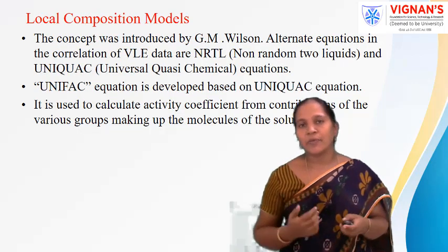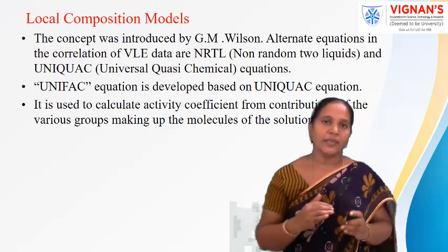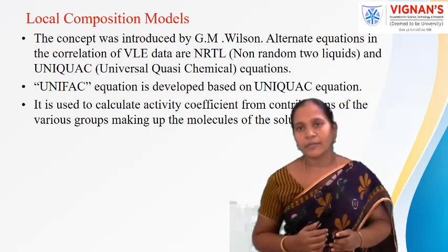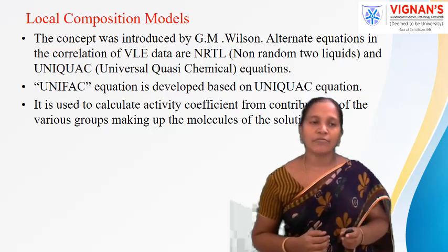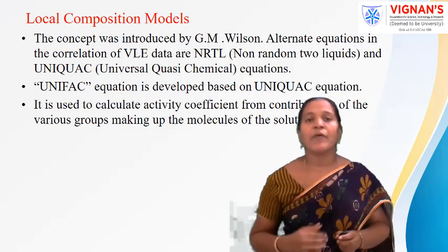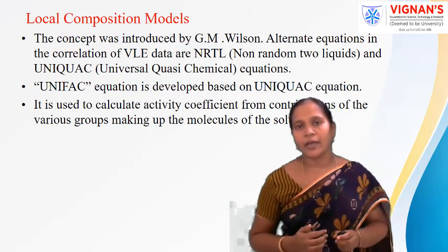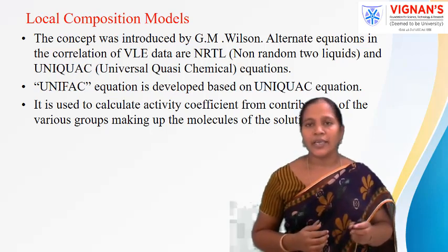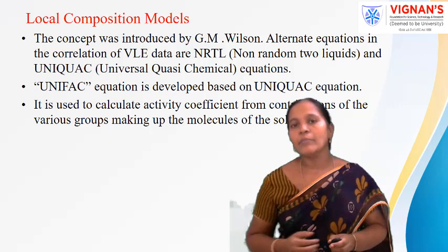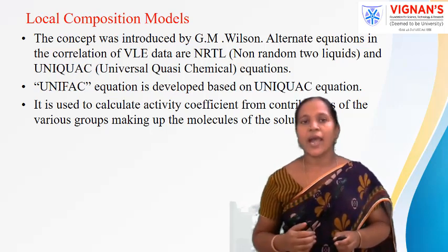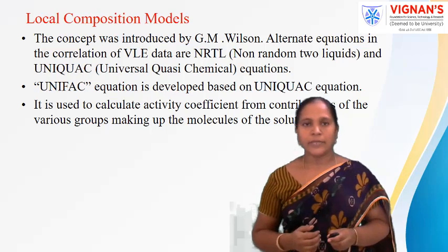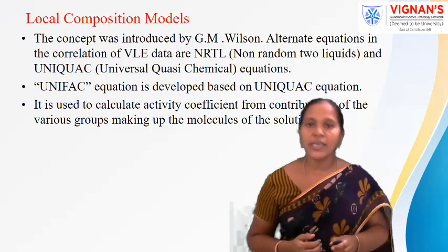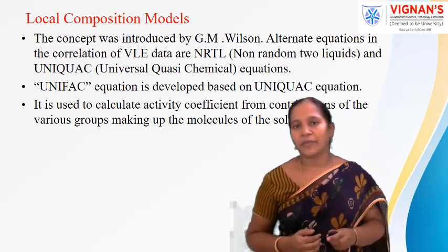The concept was introduced by G.M. Wilson. Alternate equations in correlation of VLE data, that means vapor liquid equilibrium data, are NRTL, which is non-random two liquids, and UNIQUAC, that means universal quasi chemical equations.